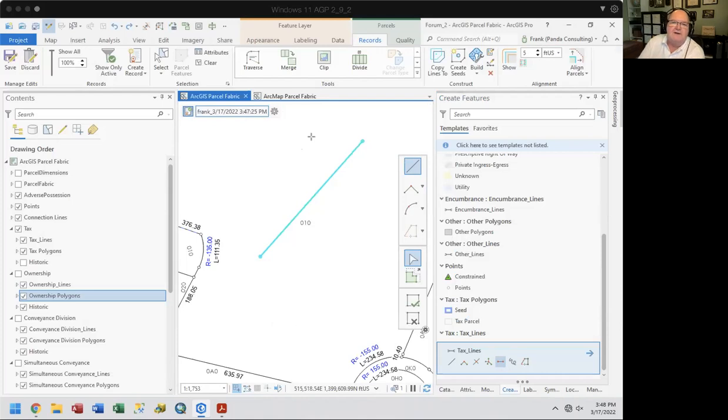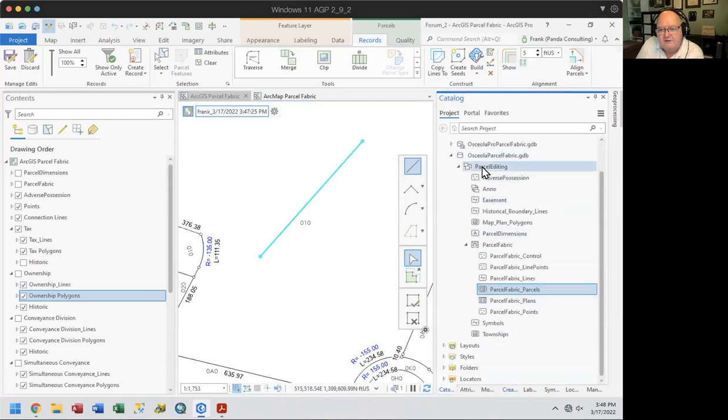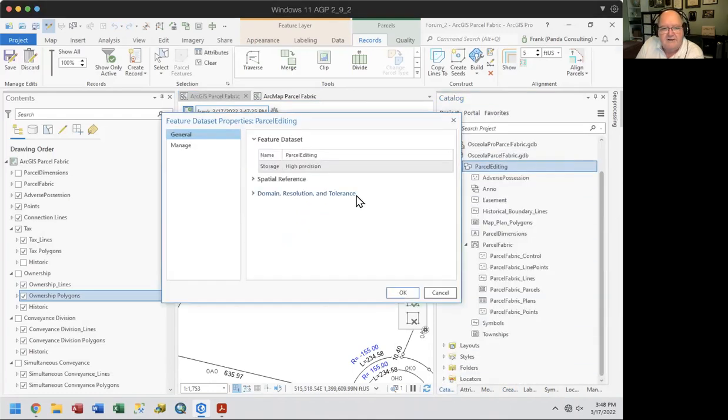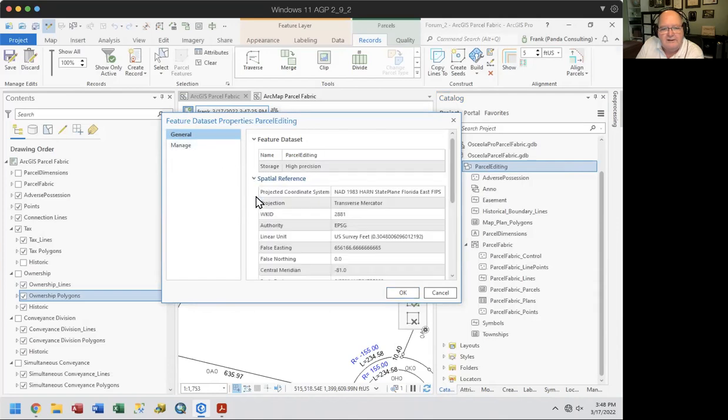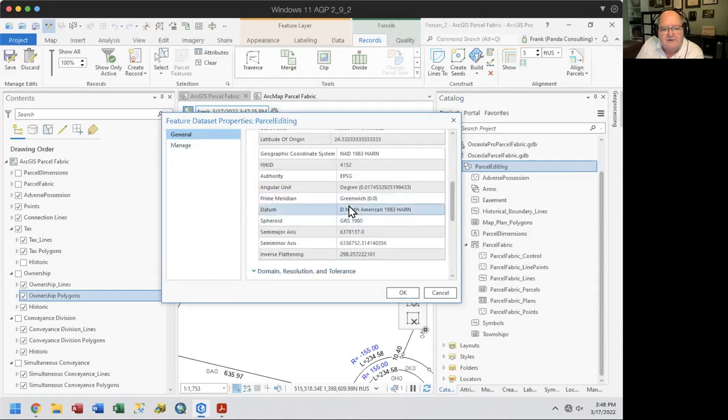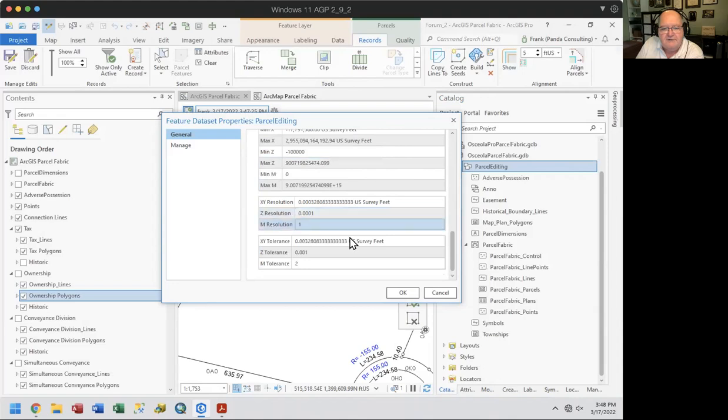The thing that we think we are seeing is that on all ArcGIS, and matter of fact, all Esri products, there is an element, inside of here, there is a setting called a resolution setting. And the resolution setting in this case is 3/1000 of a foot.